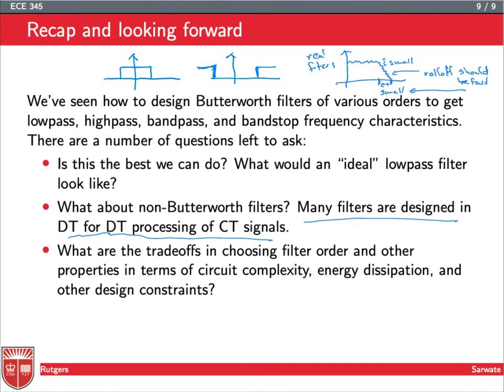But what I want to introduce really here, and what I want you to take away from this, is the idea of these different types of filters: bandpass and low-pass and high-pass, and something a little bit about what the difference is between, say, this low-pass filter here, this ideal low-pass filter that's given by this essentially rectangle function. And remember, this is the omega axis. Versus like what you actually see in reality, this kind of slightly messier filters which might not have perfect characteristics.